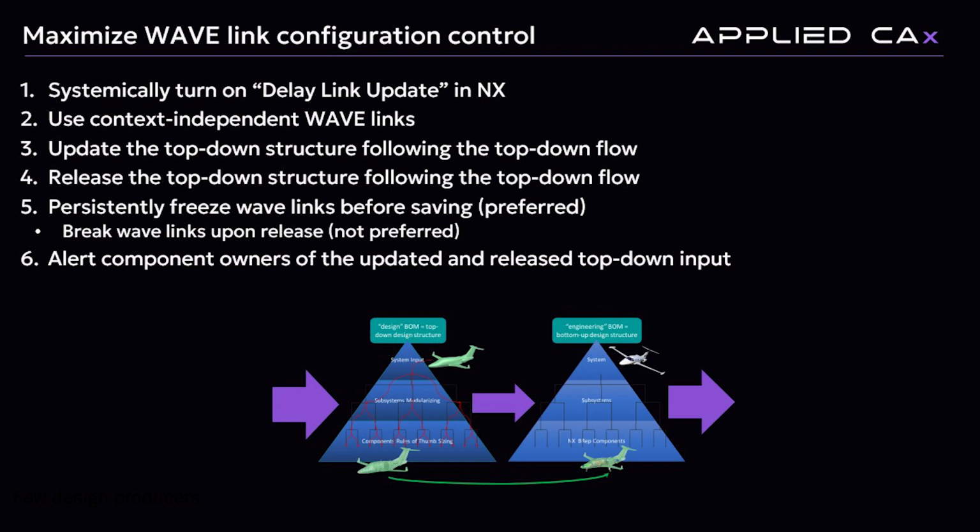Some tips for reducing load times: every time you make a change, you don't want to wait for that change to take effect throughout the assembly that you have open. So delay link update, that's going to save you a lot of pain. Otherwise, every time you change something, it's going to be thinking and processing.